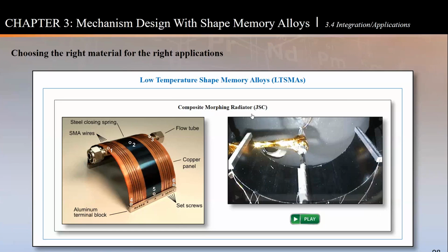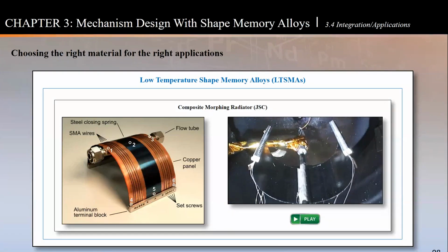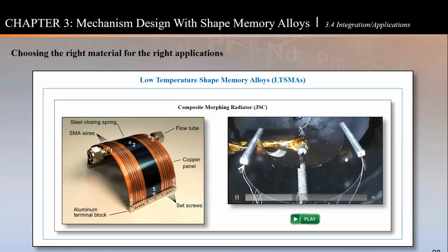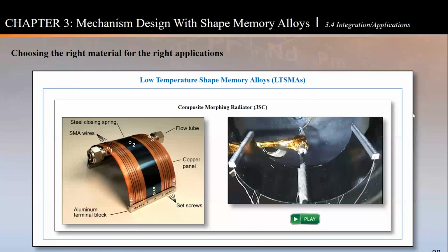This is another application with our friends at Johnson, in collaboration with Texas A&M and Paragon: space radiators. So these SMAs close and open the radiator to expose more or less of the skin, so you can change your heat transfer coefficient. Emissivity changes, and you change your radiator turn down ratios, really. So SMAs are attached, and you can close it or open it depending on what the temperatures are doing. And this is the work being done with Johnson. I showed you this, but again, these are just examples.